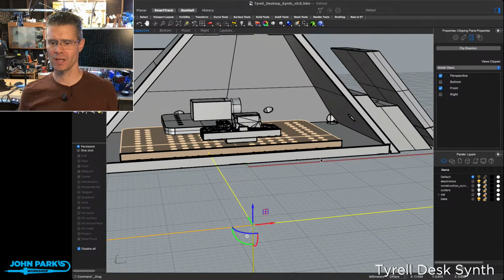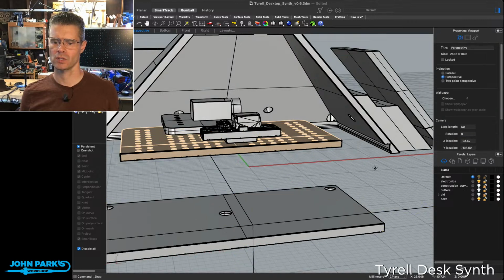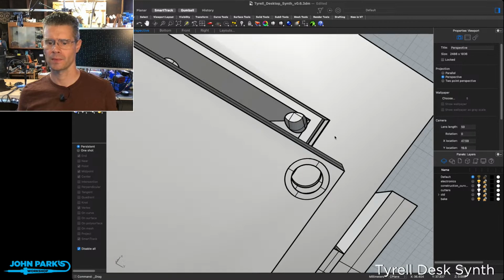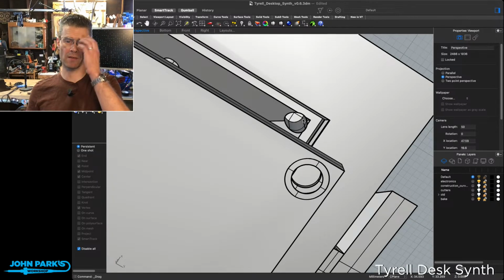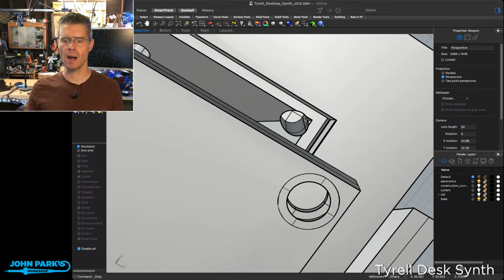These are the holes that I mentioned. Let me just move that out of the way. So the mounting holes that I mentioned, I just made them 2.7 millimeter, which is the size of the hole that I just put the screw through. That means it won't grab the screw. So I will probably do two versions, one with threading, even though at 0.15 millimeter layer height, that threading is a little rough.